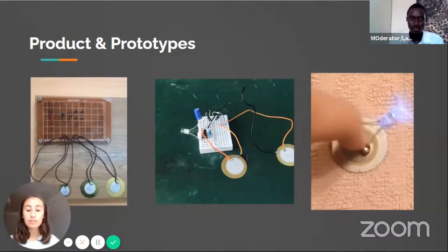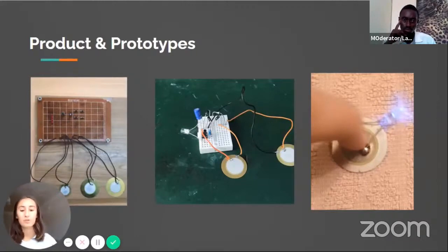The main element required to take advantage of this applied force is piezoelectric sensors. It is a device that measures change in pressure and converts it into electrical charge. Each time laptop users start typing, the piezoelectric sensors placed on their keyboard buttons store the energy with the help of capacitors in rechargeable batteries. The users can easily see the approximate amount of time that the energy on the battery will keep working. Once the wireless keyboard is connected to a computer, anyone can monitor the statistics of the battery from their computers. And you can see our 3 prototypes in order in this picture.